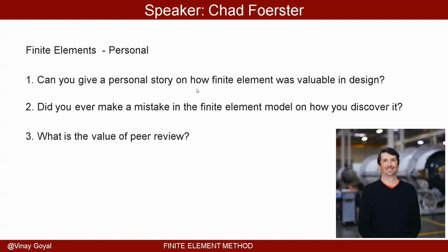And I would say in those situations, if you feel like you're chasing your tail, and sometimes it's a gut feeling, step back, try to do a hand calculation for what you're doing. Something simple. Go back to your mechanics of materials and just ask, does this make sense? If something is this thick and I'm putting this much force on it, or this much pressure, and it's at this temperature, should it be deflecting this much? Does that make sense, right?